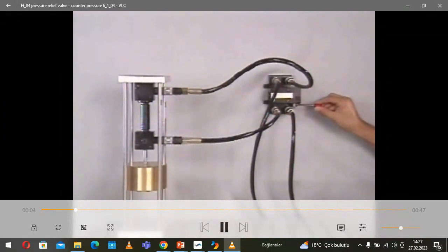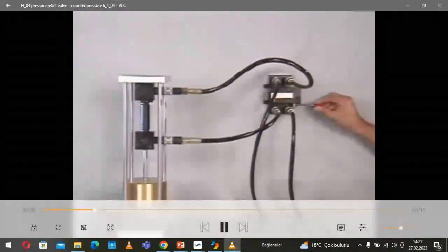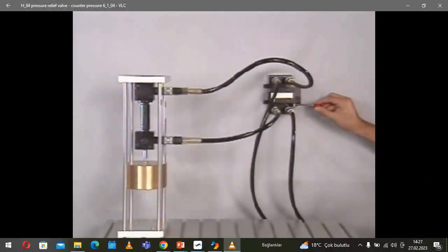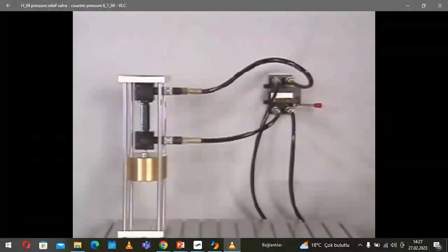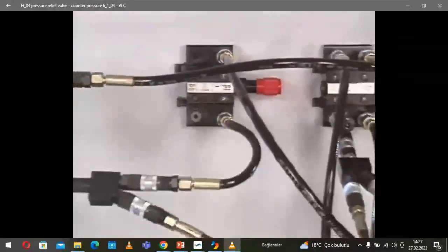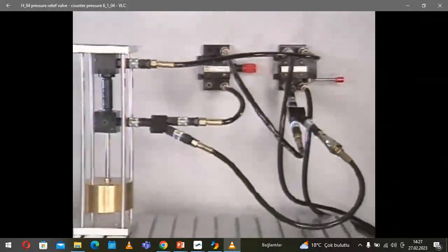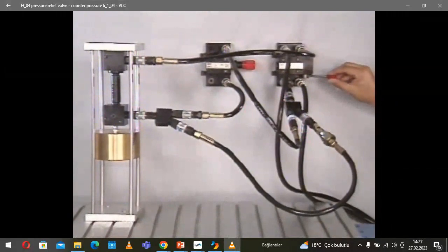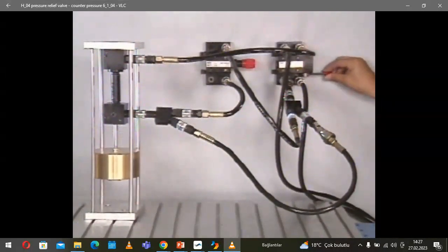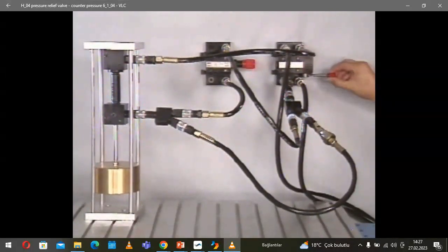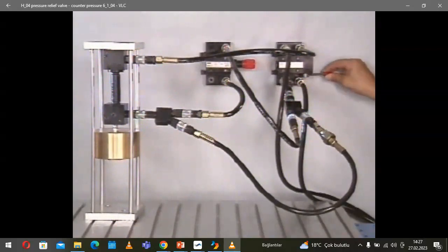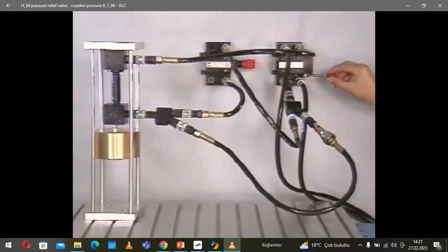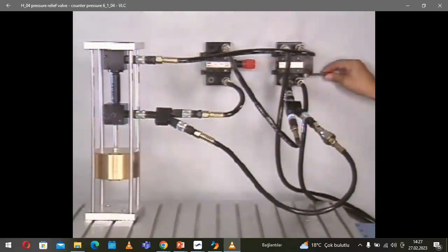When a load has to be pulled, the piston can drop uncontrolled during the switching process. A pressure relief valve can prevent this. The valve is put into the line for the outflowing oil and set for the load. This means that it serves as a counter-pressure valve. Not until pressure is applied to the cylinder does it advance. For the piston to retract, the pressure relief valve must be bypassed with a check valve.